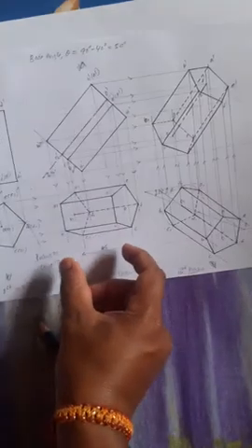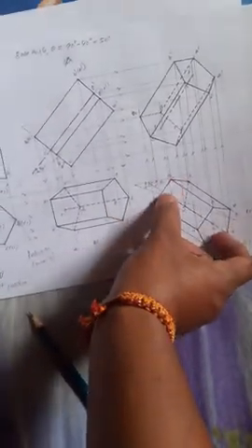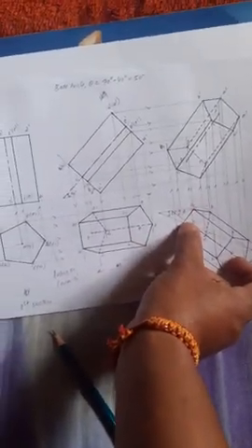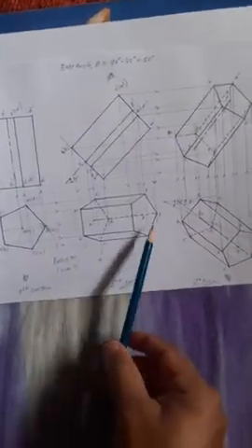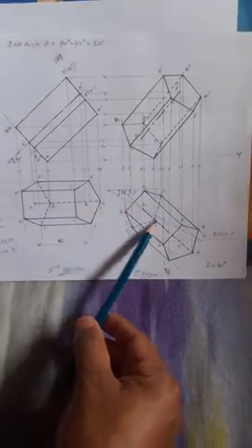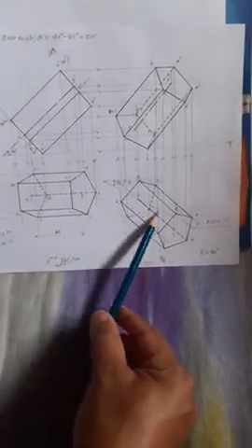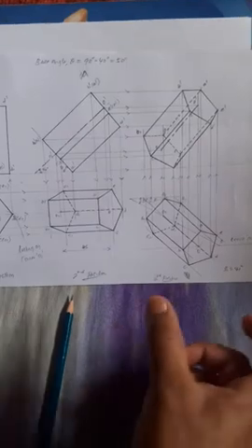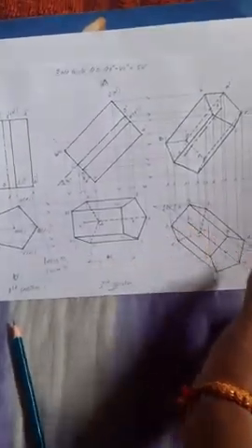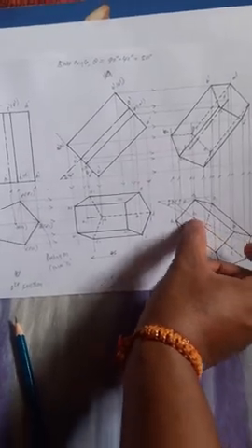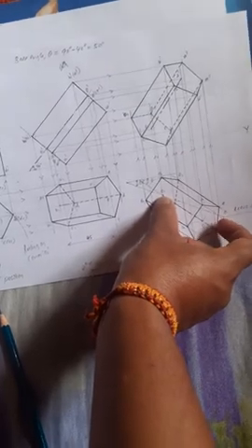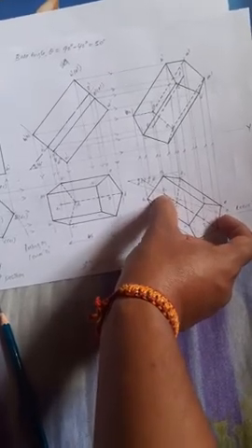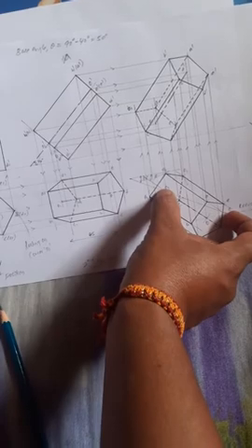On the 30 degree line, if you directly place 45 mm, it is wrong, because the true length is not there. Then it comes under what? Beta method, right? Once it is beta method, first draw a 30 degree line. On the 30 degree line, what is the true length of the axis? The true length of the axis is 60 mm. Mark any one point O1 on the 30 degree line and draw an arc of 60 mm radius on the 30 degree line. That O1 O you get is 60 mm.